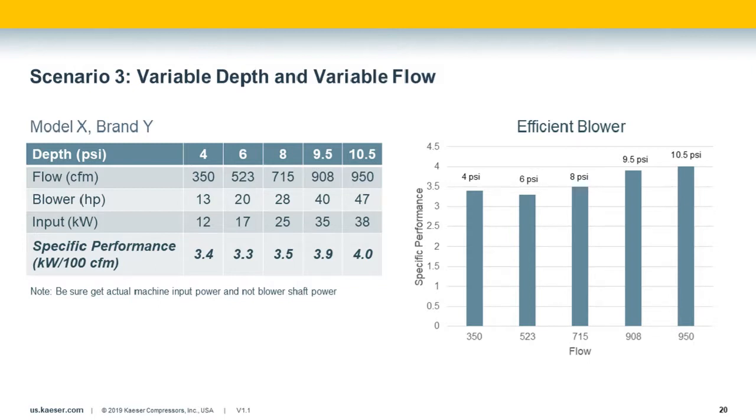If you don't get the 5-point curve for each pressure, then you have to do all the interpolation. So in this scenario, we just requested flows at a given pressure and got them from the manufacturer. Otherwise, you have to do interpolation. So here, we sourced the data for desired points, which simplifies the effort on this example.